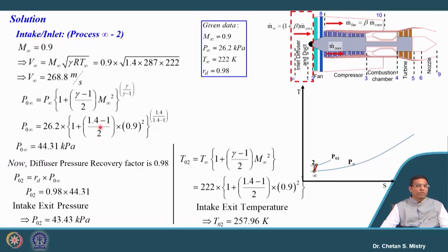So, I am sure you are aware of this. If you make a mistake in the calculation, and if you forget to put this Mach number, the whole pressure and temperature at the exit of your intake will be wrong. That means all your cycle parameters will go wrong, and that will give you a wrong value of exit velocity.